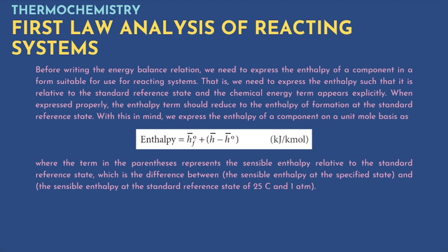With this in mind, we express the enthalpy of a component on a unit mole basis as the formula shown below, where the term in the parentheses represents the sensible enthalpy relative to the standard reference state, which is the difference between the sensible enthalpy at the specified state and the sensible enthalpy at the standard reference state of 25 Celsius and 1 atm.